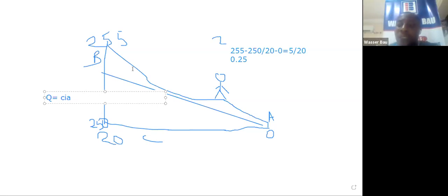Now, for your design, you are going to use the surface as a reference. The survey data you have are surface data, so you design your pipe as if it is going to lay on the surface. Then when you are doing your computation, you take an offset of between 0.6 and 1.2 meters. That's our standard here. But in Europe, because of snow and freezing, you can go as deep as 2 meters.